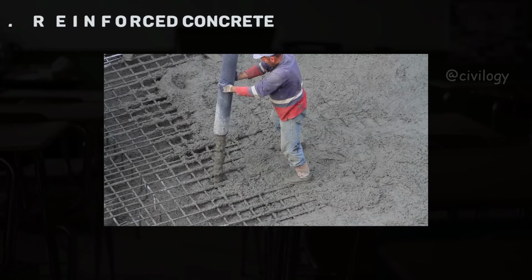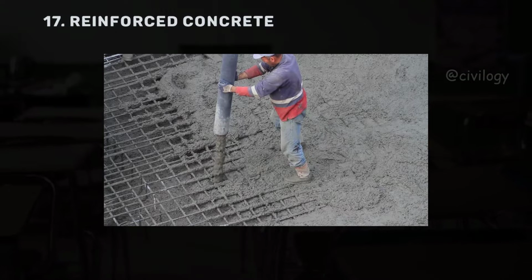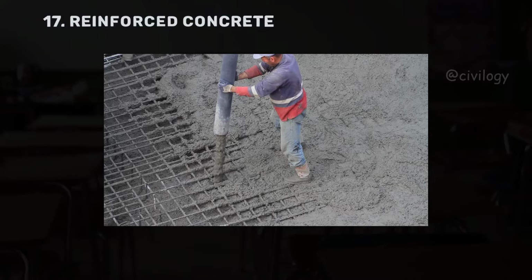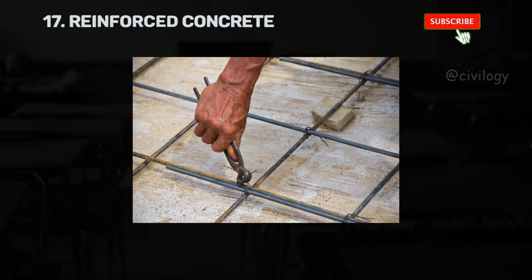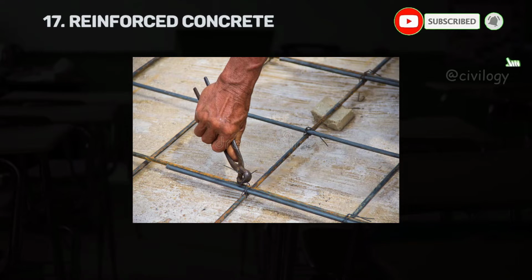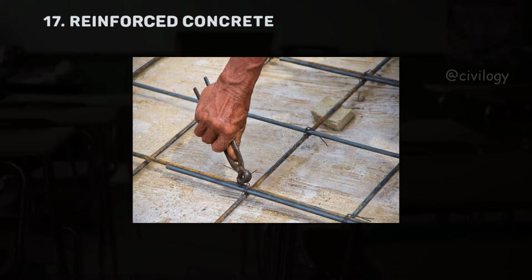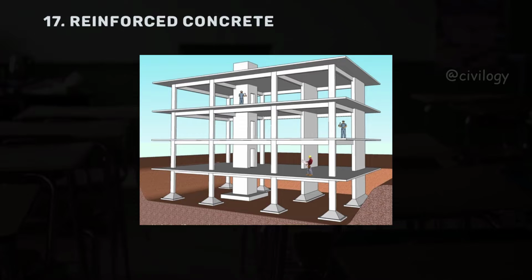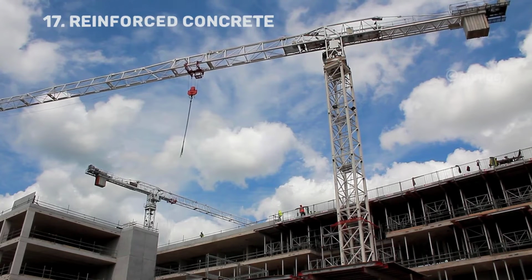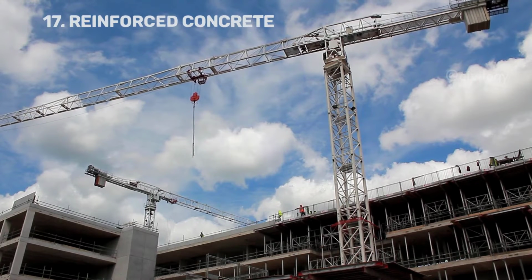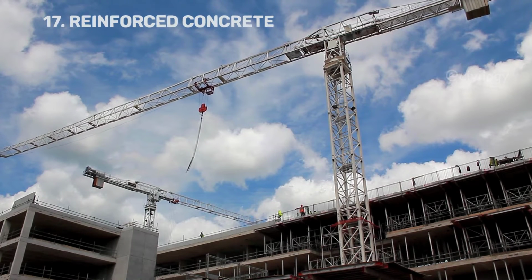And next, reinforced concrete. It is also known as RCC, and steel in various forms is used as reinforcement in the RCC to give very high tensile strength. So every care is taken to ensure the maximum bond between reinforcement and the concrete during setting and hardening process, because the resulting material is capable of bearing all types of stress in any type of construction. So the stress may be in the form of tensile stress or compression. RCC is used in almost every house construction, especially in India.